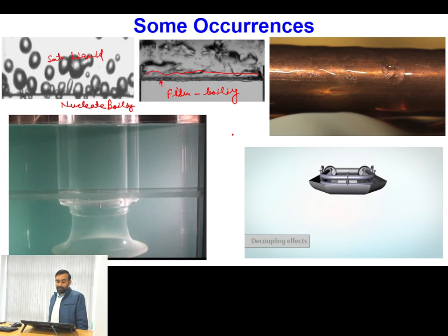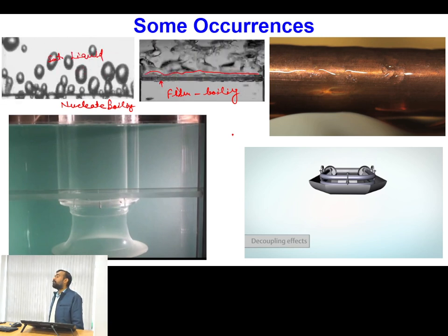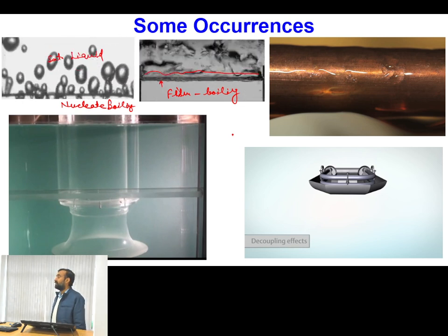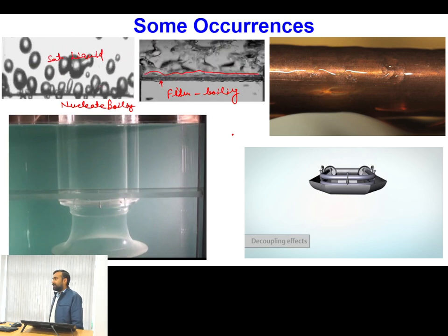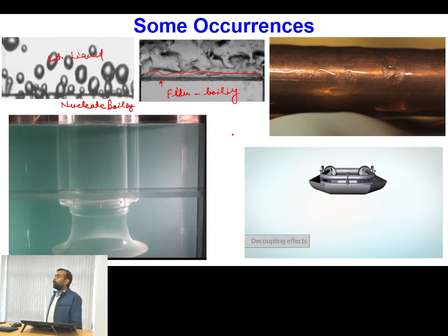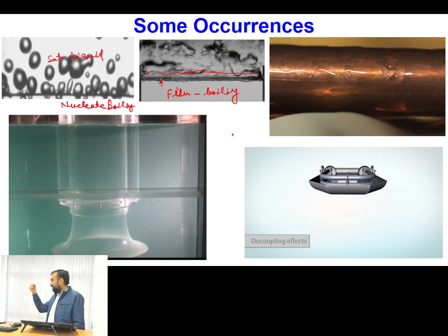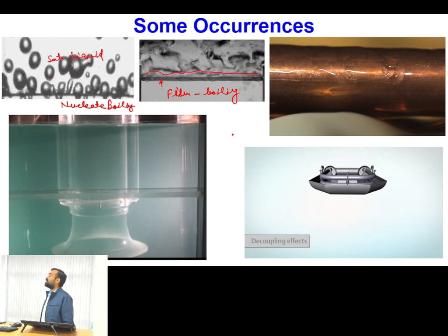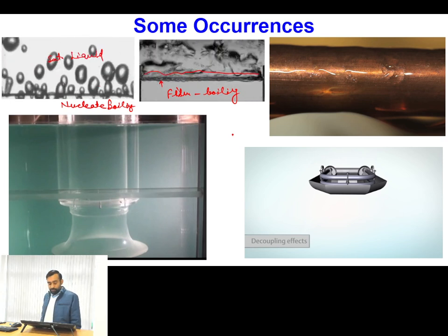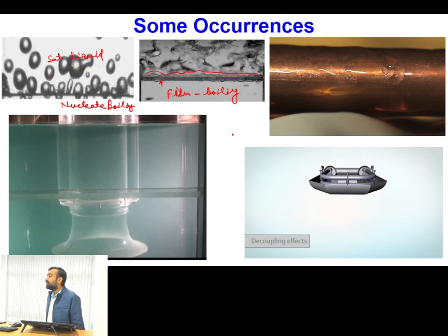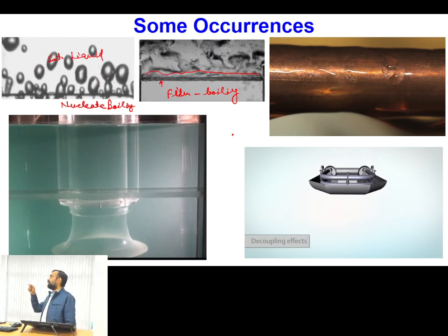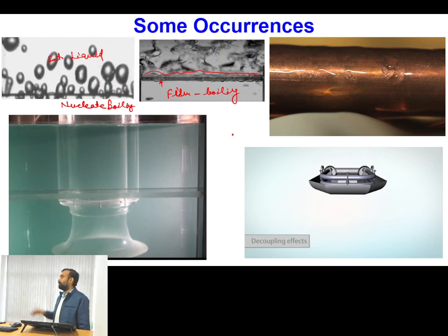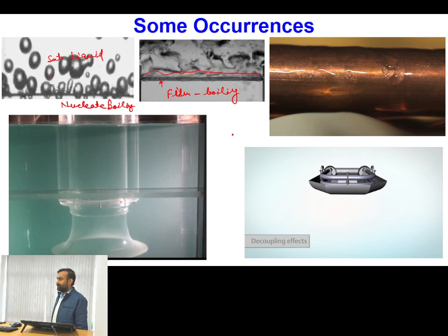Okay, so in these scenarios you will find, first thing, that your pumps operate round the clock, and if in these types of pumps this air entry happens, then the overall life of the pump will be very less. Second important point is, if we want to achieve the desired flow rate, if we want to set the flow rate to control certain processes existing downstream of the pump. Okay, so if entry of air is taking place, this can cause fluctuations in flow rate of the liquid, and if we have fluctuations in flow rate of the liquid, then ultimately we will not be able to achieve our task with the desired composition.